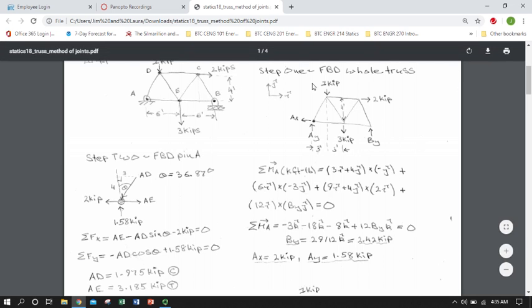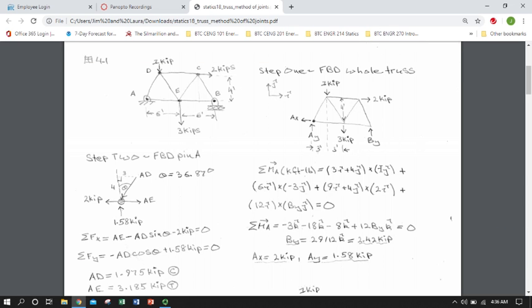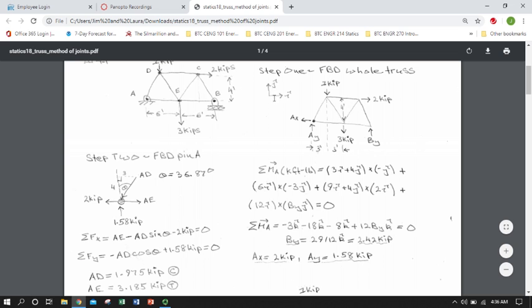In the case of force number 1, I knew I was 3 feet in the x and 4 feet in the y from the point of application, and I had a 1 kip downward force in the j direction, skipping the units in this expression, given my j and i. Then I'm going to add the moment from this 3 kip force.